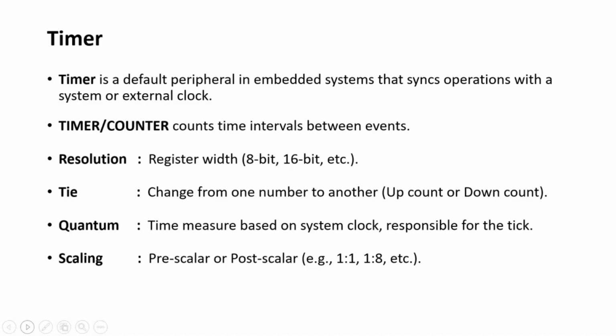Timer. Timer is the default peripheral in an embedded system that scans operations with a system or external clock. Timer or counter counts the time interval between the events. Resolution is also called the register width. It is 8-bit or 16-bit, etc. Tick. Change from one number to another number, such as up count or down count. Quantum. Time measured based on system clock, responsible for tick.